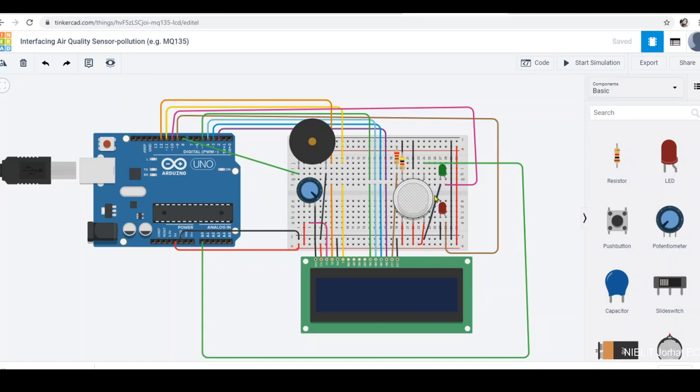Now basically, this gas sensor can sense nitrogen oxide, carbon dioxide, and some polluting gases. When it is over polluted, a certain level will be reached, and according to that level we'll get the beep sound or a signal here. So we have to at first take a threshold, that after this value we can consider the air to be polluted, and below this level the air is unpolluted. Okay, so the connections I will show you now.